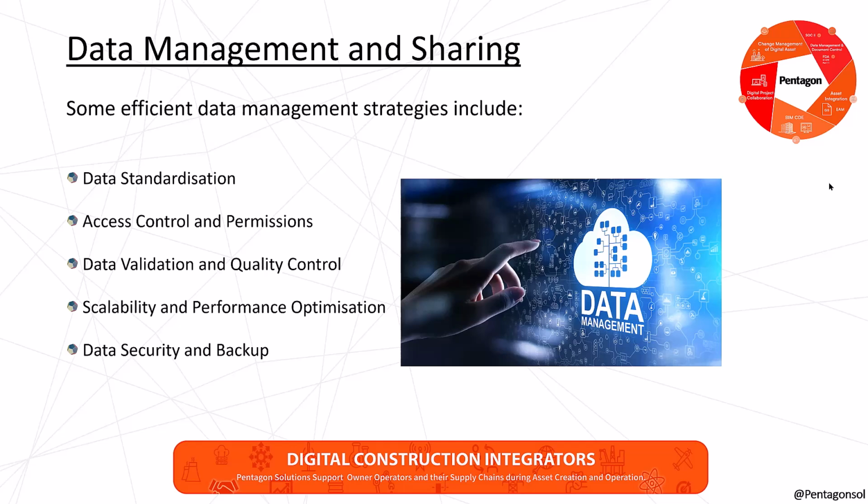For efficient data management strategies, there are a few different strategies which must be noted to ensure data management is done safely and efficiently within BIM collaboration tools. So data standardization, so you want standard file formats like IFC to ensure interoperability between BIM authoring tools and platforms. Metadata and naming conventions, so establish consistent metadata standards and naming conventions to improve data organization. Again, we also want access control and permissions, so role-based access, so define roles and permissions of who can view, edit, and manage different types of data. And again, we want audit trails, so we want to track changes and data access, which helps maintain data integrity and accountability, which is a big thing for ISO 19650.